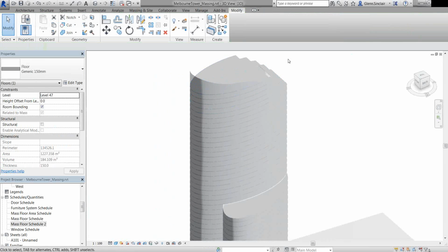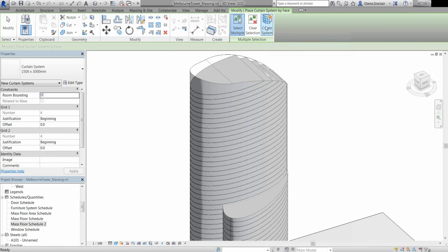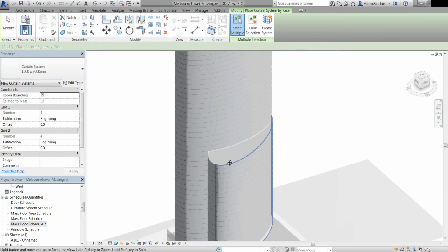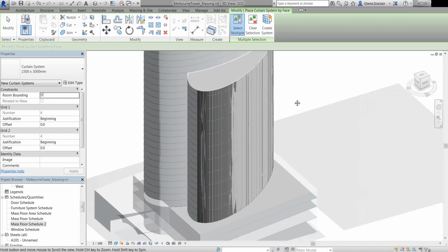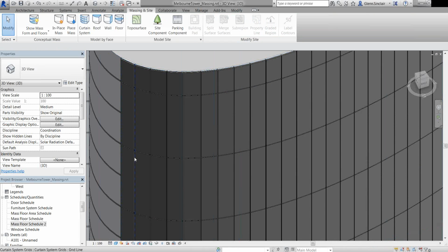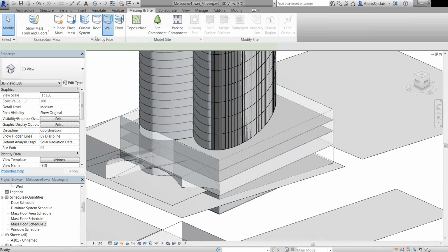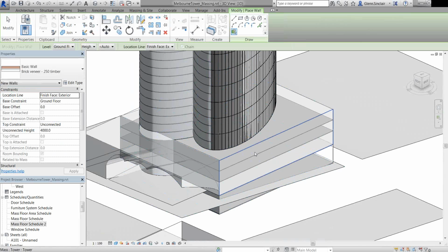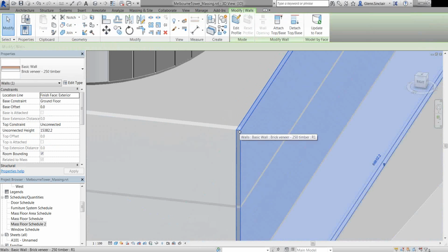We can also use the walls, the vertical surfaces, I suppose, as walls. So we'll click the curtain wall tool, set up the options of the tool, and use those faces as the base for a curtain wall system, and also roofs and solid walls as well, not just curtain walls. So there we've got a glazing system with mullions and 1500 transoms at, what is it, 3 meters or something. So we use the mass as the base for our project there. Let's just go ahead and turn that into a solid wall.